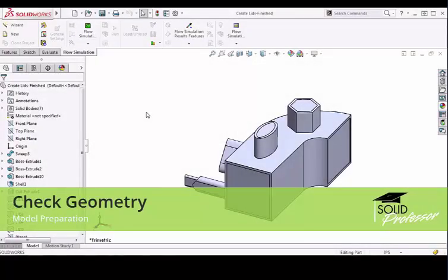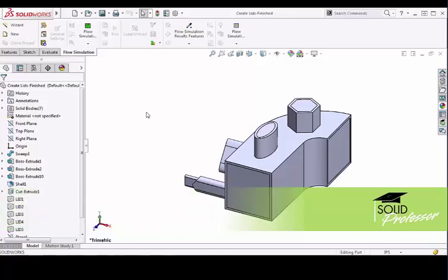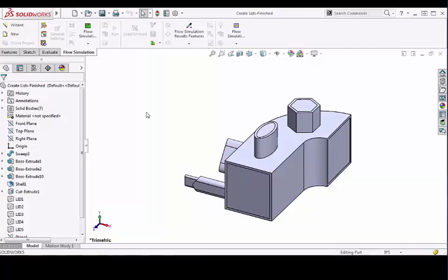If you remember from the previous lessons on manually creating lids, we used a mid-plane option for the extrusions when creating the lids. Now, I mentioned that the reason for doing this was because using a blind option would create an invalid contact later on. Let's take a closer look at what this means.